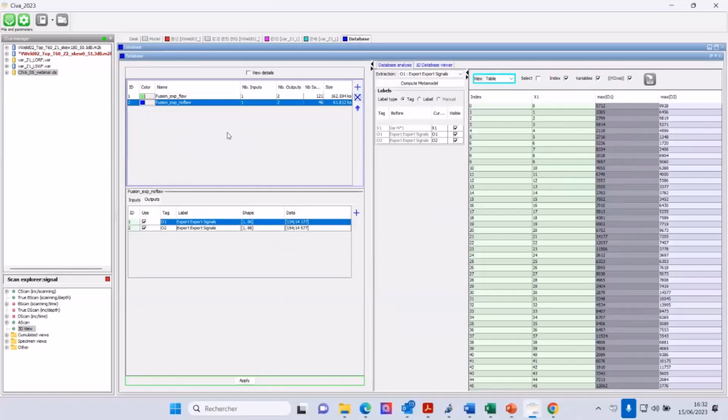When you run a simulation, you have what we call the amplitude in CIVA points, and when you load experimental data, the amplitude in points is not the same. So there is an additional step when you want to compare and merge experimental and simulated data: calibration and normalization. To be comparable, the simulation and experimental databases should be calibrated.